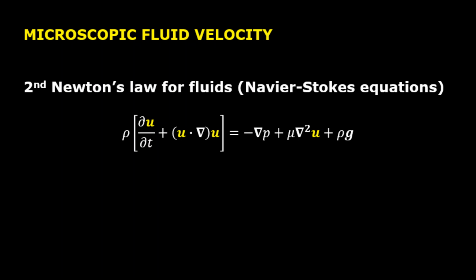So in this case, in a fluid, we have different forces behind the fluid flow, which are the pressure forces, which is represented by that minus gradient of the pressure. We have viscous forces, so that's the third term, viscosity times the Laplacian of the velocity. And then we have gravitational forces, which is the last term in the Navier-Stokes equation. As you can see, density times gravity.